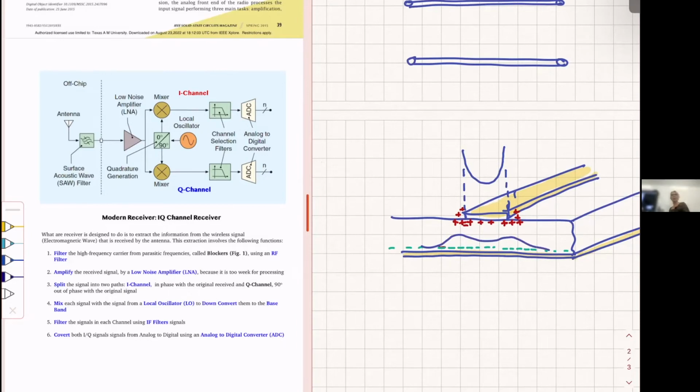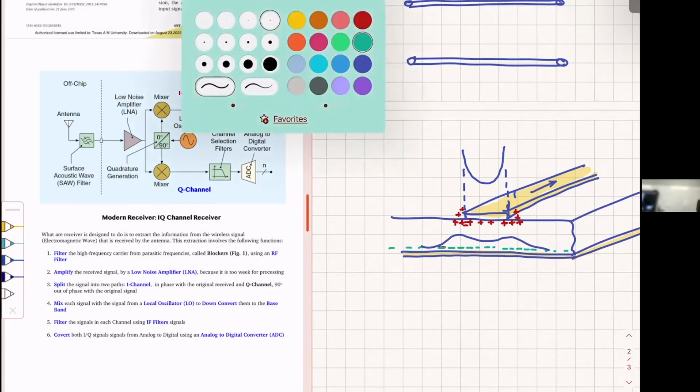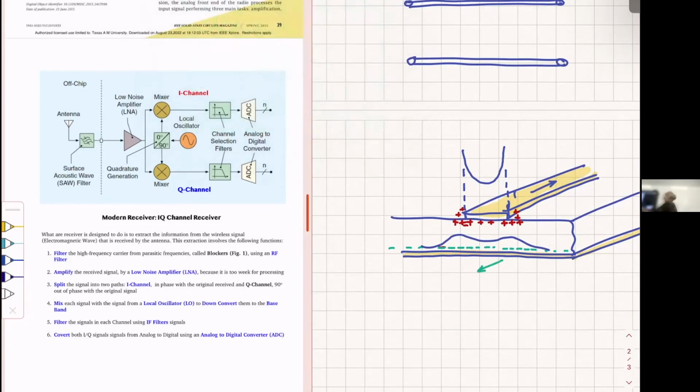Something like this. But they are going to be, maybe a little more sharp here, somewhere underneath it, which means that if my current on top goes like this, I'm going to have a return current on the bottom that is going to look like this. Granted, it's going to be a little further out distributed, but there I can see the return current in the ground. So practically one infinite ground with a strip on top makes a 2-wire line. Okay, that's the microstrip. We use it extensively.